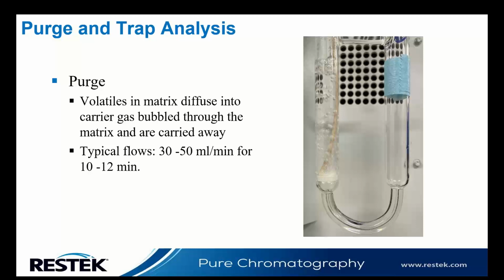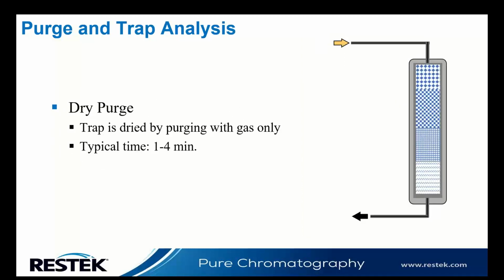A lot of method specific requirements have you at 10 minutes. And you will notice if you're purging, again, at ambient, you'll lose the hexachlorobutadiene and naphthalene, some of those heavier compounds, if you're not purging for a long enough time.